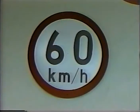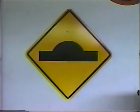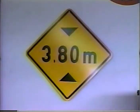Lastly, let's look at the Latin American system. In general, regulatory signs, again with the exception of stop and give way signs, are circular. Black symbols or diagrams on a white background with a red border convey the intended regulation. Warning signs are diamond-shaped. They have a black symbol or diagram on a yellow background. An exception to the diamond shape is the crossbuck shape at railroad crossings.